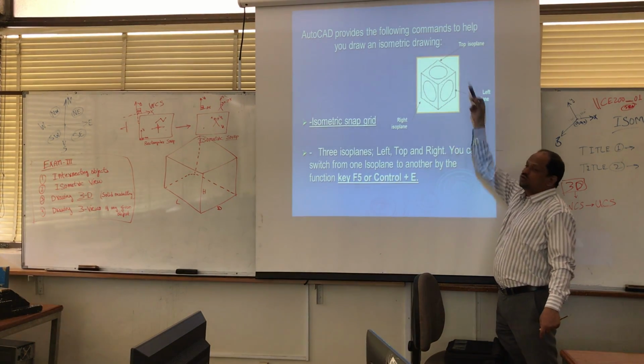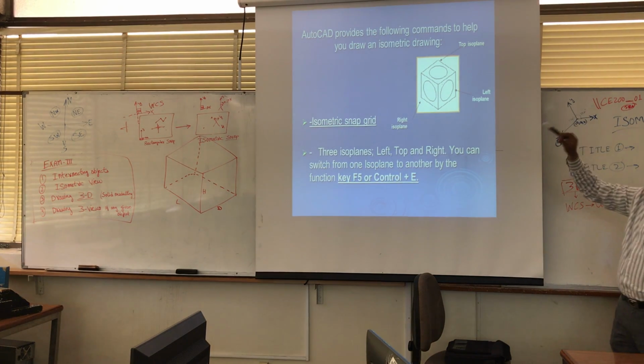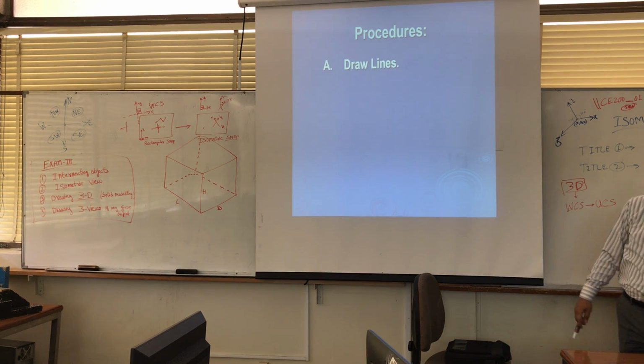I finish. Then I want to draw at the top. Press F5. It moves there. Again F5. It moves here. So it moves from one plane to another. I will show by opening AutoCAD, but just follow the procedure first.